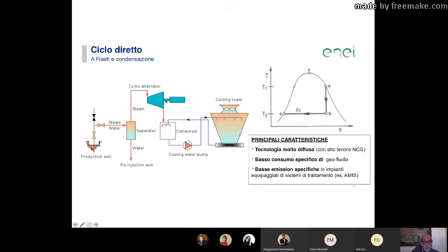So the vapor through the turbine is condensed right on the back of the turbine, creating a depression that goes well below atmospheric pressure. And by doing this, you're actually recovering the enthalpy of vaporization, which is the largest energy content.